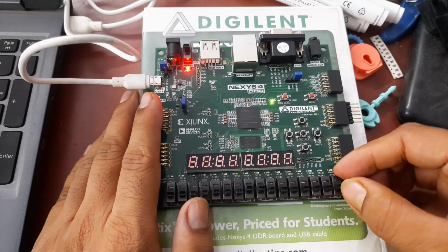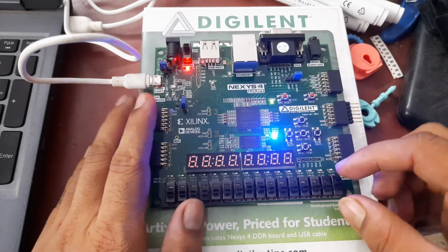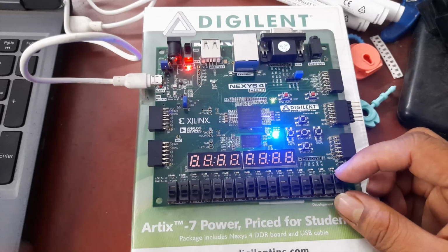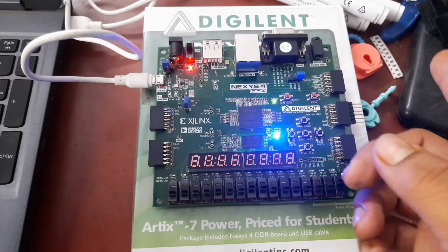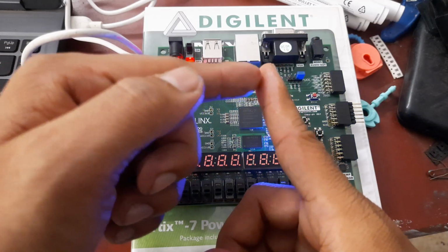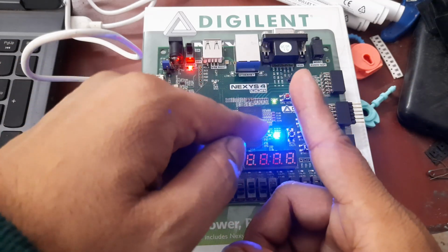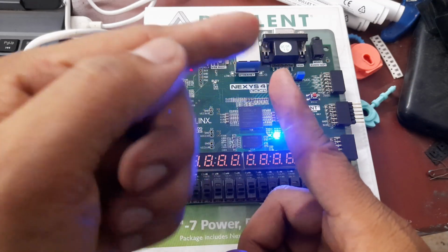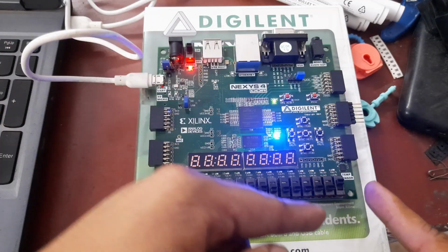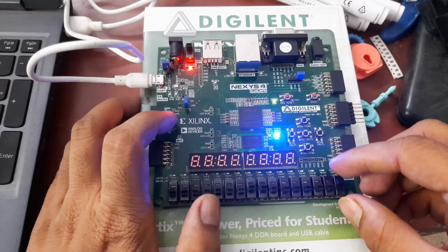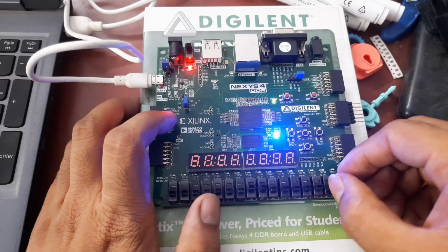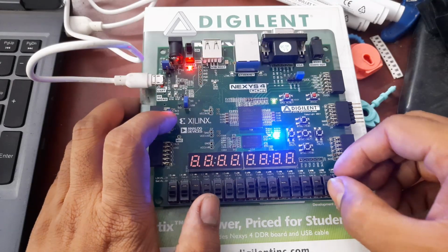And again, the clock is very high speed over here, so that is why we are instantly seeing the effect. What is going to happen until the next positive edge comes, this is going to remain in the previous state only, and as soon as the next positive edge is hit, the S is equal to 1 effect will be shown, right? But since here the clock is so fast, the effect is shown immediately, okay?